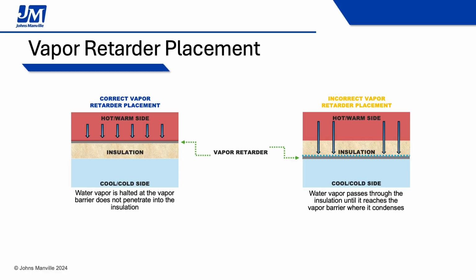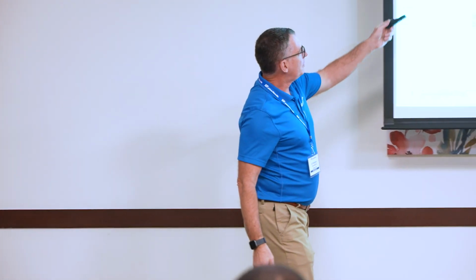If we think about it, we want to keep water vapor from moving from where it is in the air to some cold surface, right? That's why we use them. And we want to make sure that we don't get condensation forming on whatever our cold thing is. For us in HVAC, it's probably an air-conditioned duct, right? So that ductwork is carrying 55-degree air off the coil. That metal is cold, right? We don't want it to start sweating.